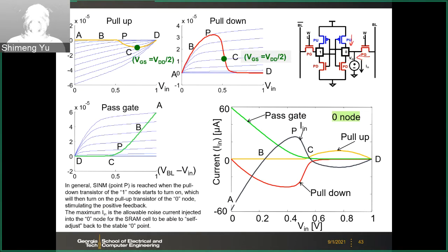Of course, you need to define the polarity of that. If you think all of them are pointing to this node, then some of them will be negative, right? Some of them will be negative. But eventually the net current after those three transistors, if you still have net current, that net current must go through the voltage source. And this is what you measured from the voltage source.